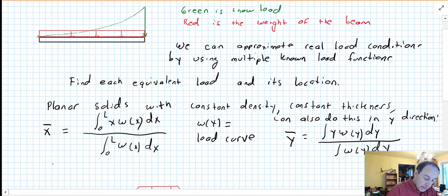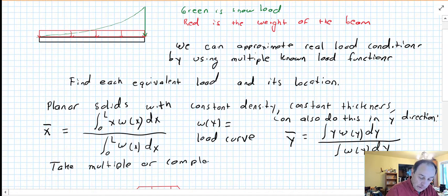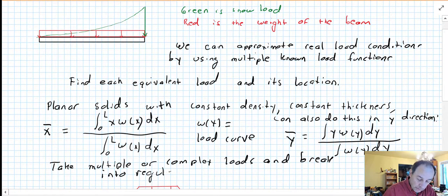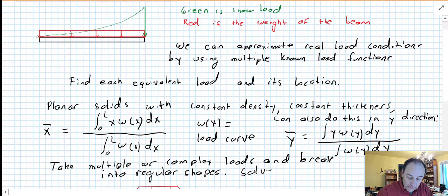So you can take multiple or complex loads and break them into regular shapes. Then you solve and add your results.